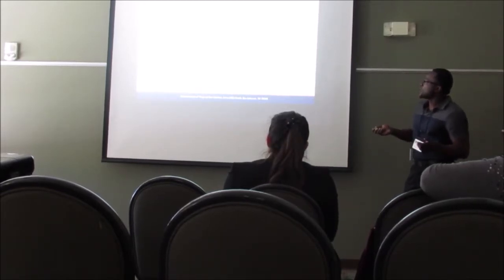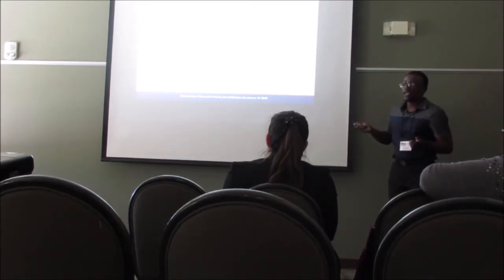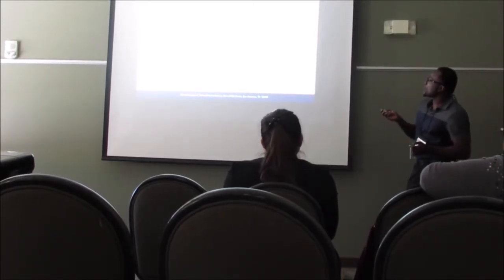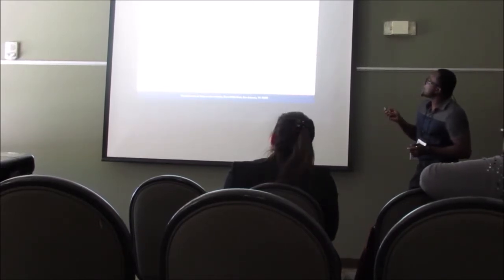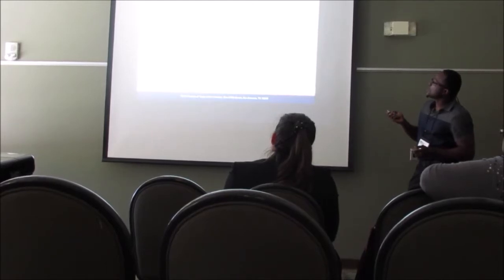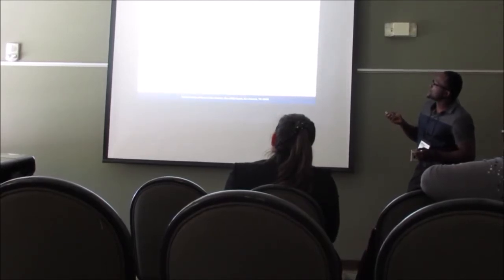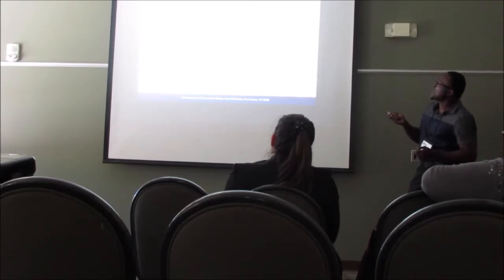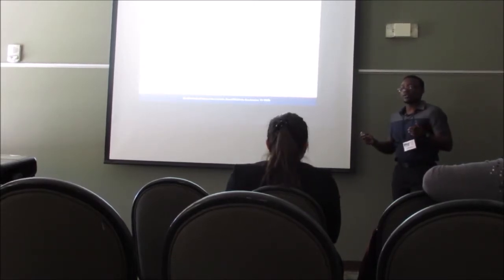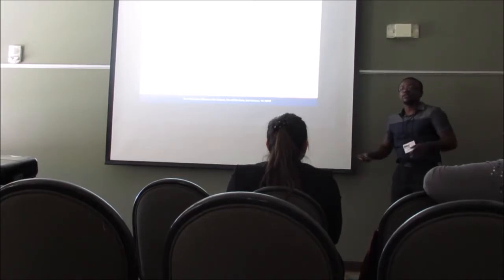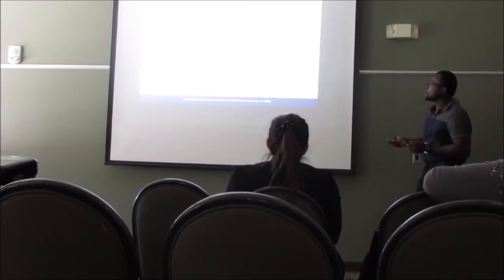For the spiral bar that we analyzed, we saw a similar type of behavior where the first flexural crack occurred at around 4,000 pounds, which is relatively the same. But what was important is that we saw a stable drift ratio. So if you look at here in the regular bar, the drift ratio is not stable. It's kind of like changing up and down. But for the spiral bar, it's a stable drift ratio, which is a good component and important for us because we want our members to deflect uniformly to let us know that something is going on, and we don't want it to just deflect, and then fail. So we want a warning before failure.